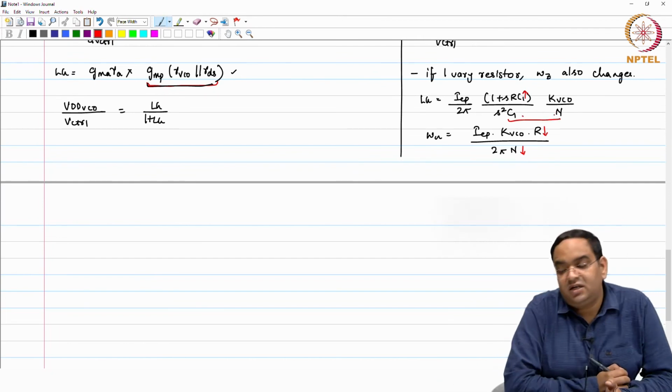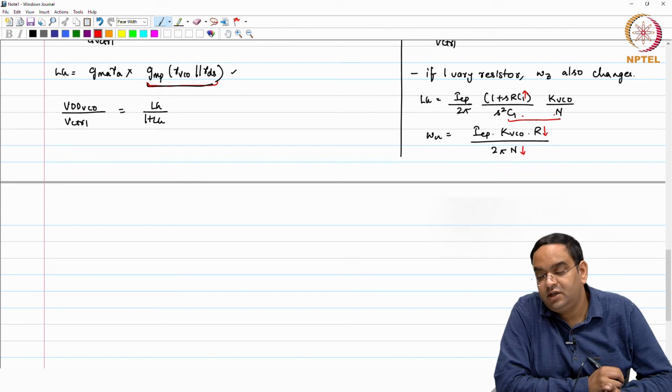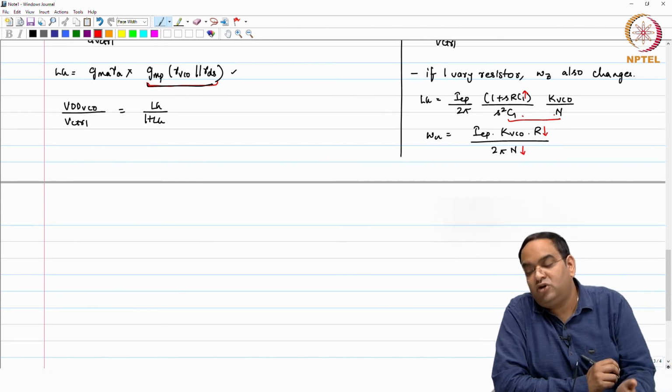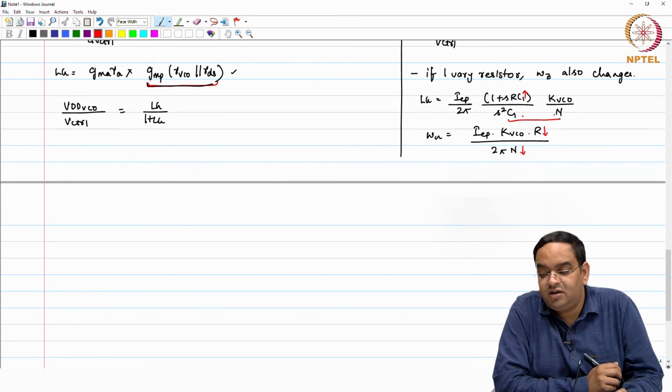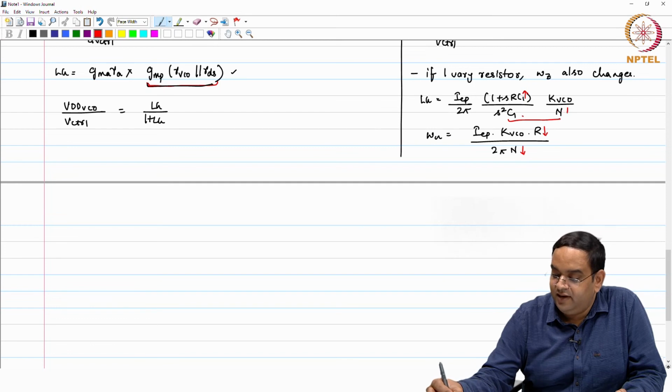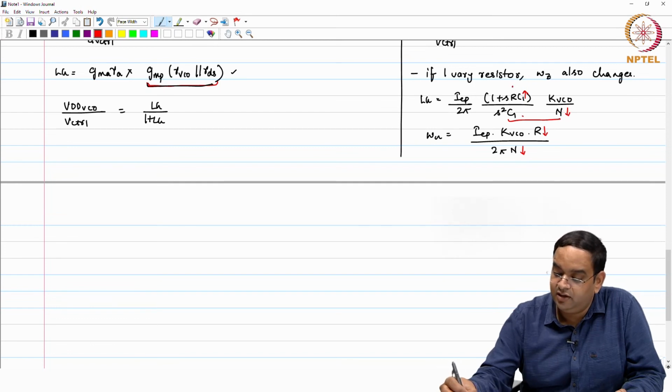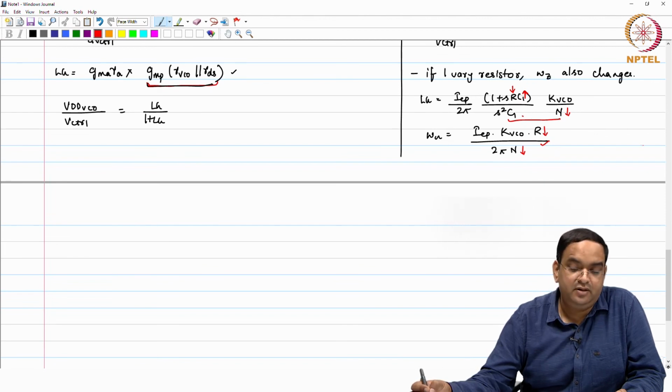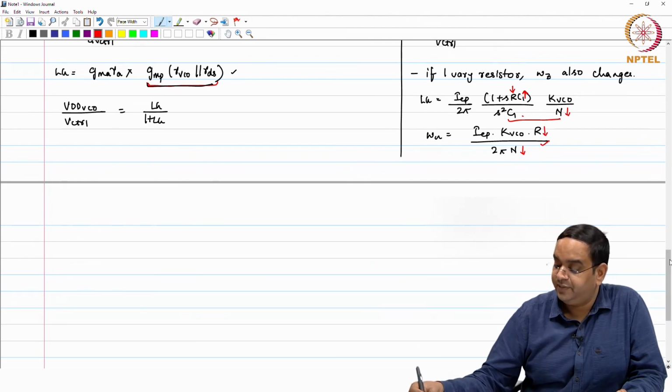So, this method of changing the resistor to compensate for the change in N is not that fruitful, because as N reduces, you reduce R. To keep the same 0 frequency, you increase C. So, okay, your bandwidth remains fixed, but what happened is your overall loop gain changes. That is what you will see.